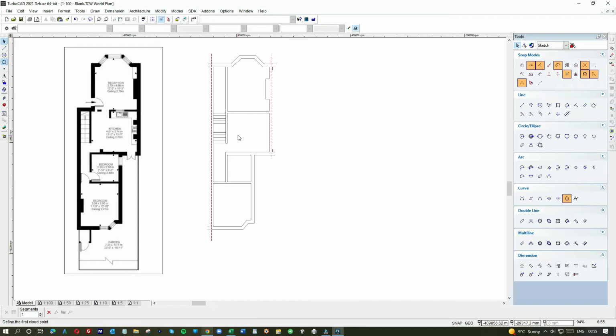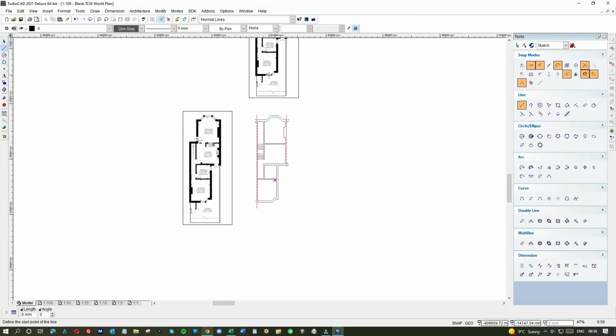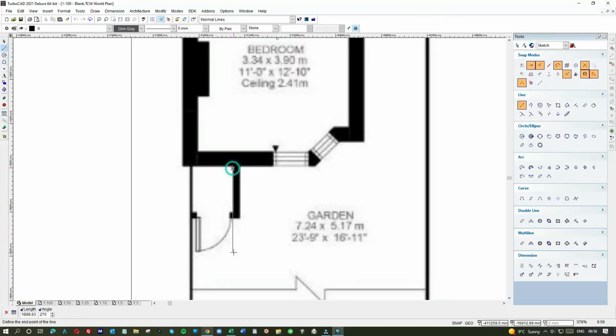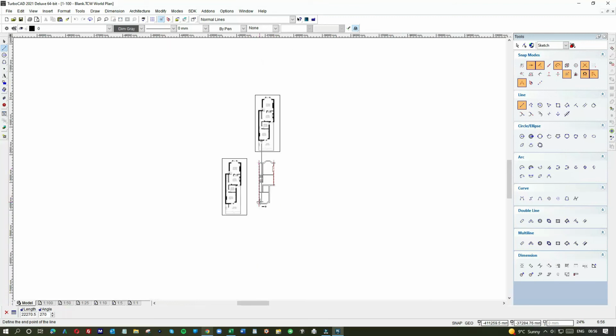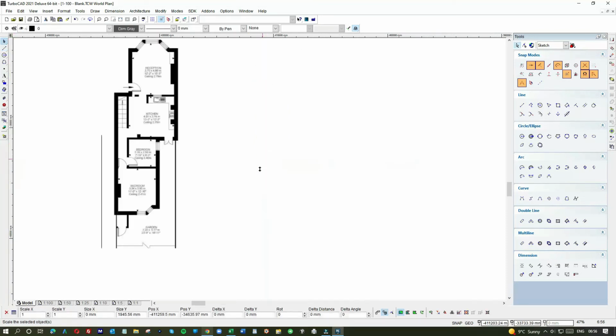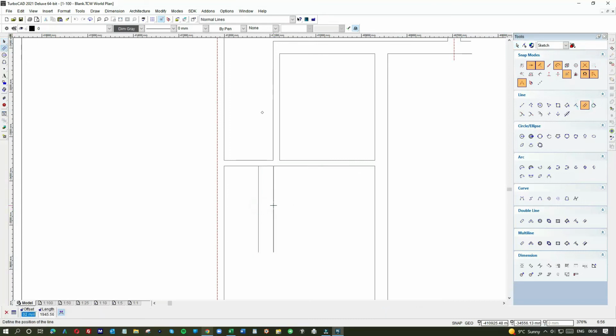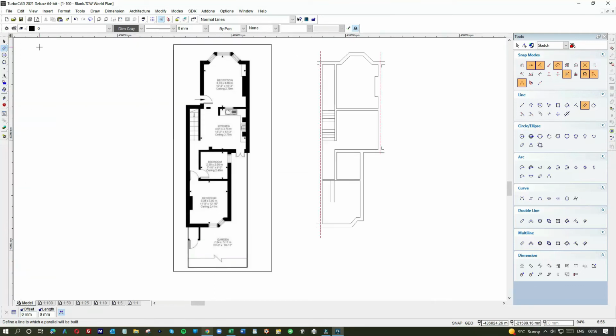Okay, overall we're looking good. Few bits and pieces to add on still. I see that we have a little outside loo here, or what used to be an outside loo, so we better add that on. Again, inside measurement preferably. And the outside loo, again, is drawn wrong because even though it was just an outside loo, they generally built it in two bricks, so it wasn't single brick. So what we should be doing is 285 here. So we go tab 285.